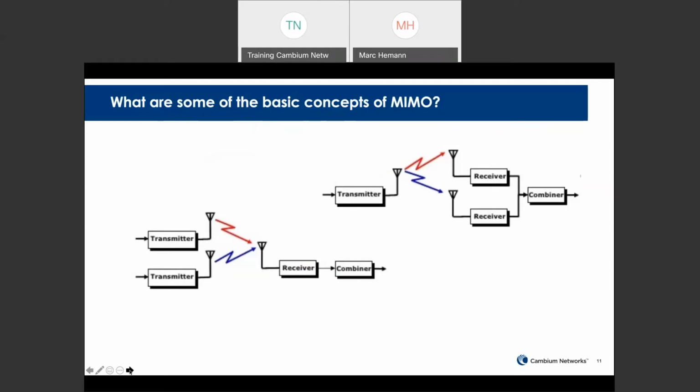The first, which I've already mentioned, is spatial multiplexing. Spatial multiplexing provides for greater throughput and takes advantage of our old nemesis, multipath. Space-time block coding and cyclic shift diversity are a couple of transmit diversity techniques where the same transmit data is sent out on multiple antennas.